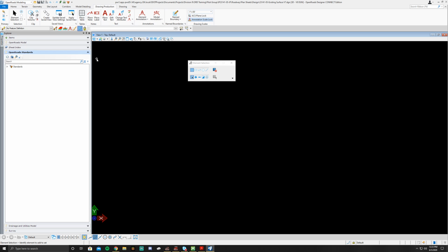Another thing that you're probably going to want to do, something that I've noticed is helpful, is keeping the Set Feature Definition button up here in the Quick Access toolbar. The way you do that is you just go here, Customize Quick Access Toolbar. You'll find the icon that's in there, add it, and then close it, and it'll pop up here.